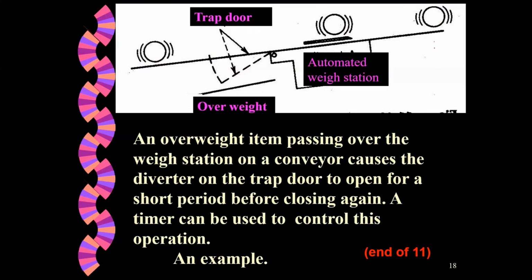And this line is going at 30 feet per minute. No switching on and off, it's continuous. When the operator pushes the button, the conveyor keeps going. So the conveyor has to pace with this 30 feet per minute. So quickly drop the ground beef, and the machine takes over, applies heat, and puts the saran wrap and heats.